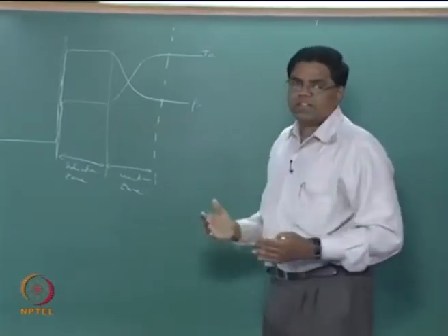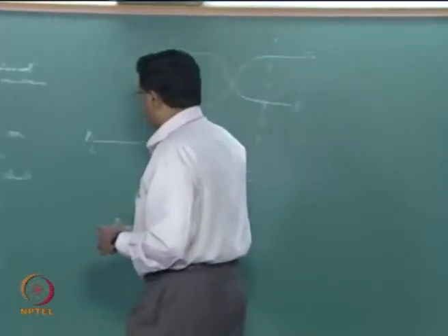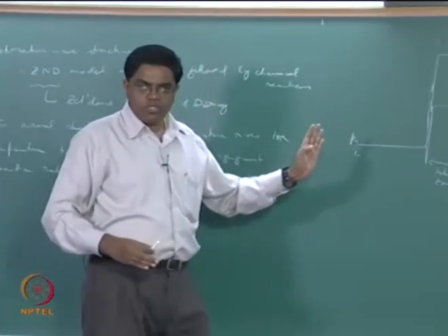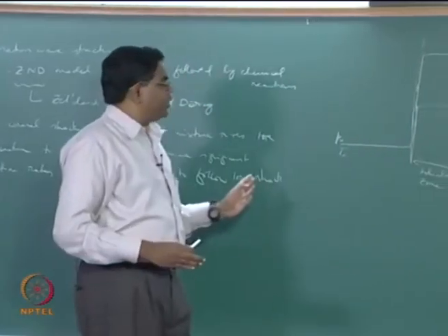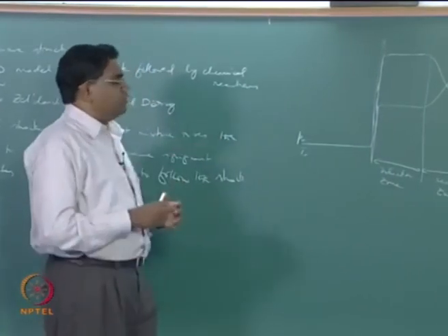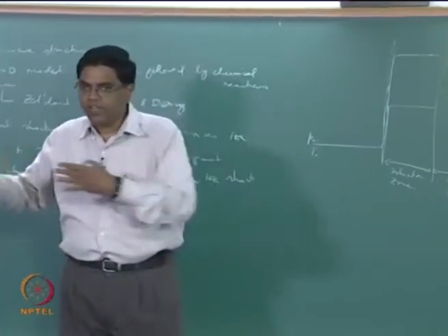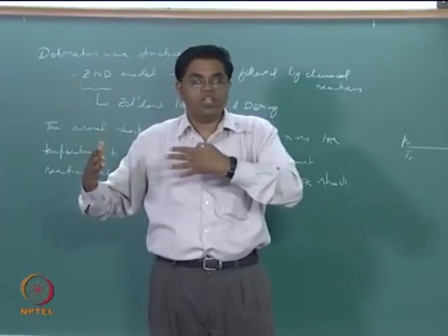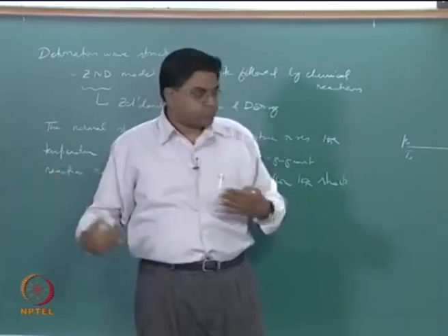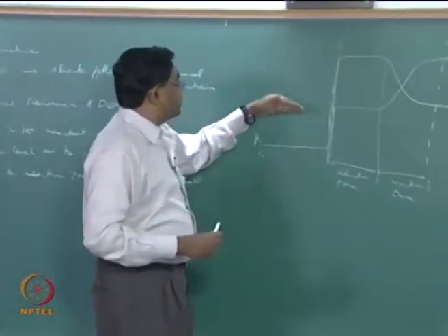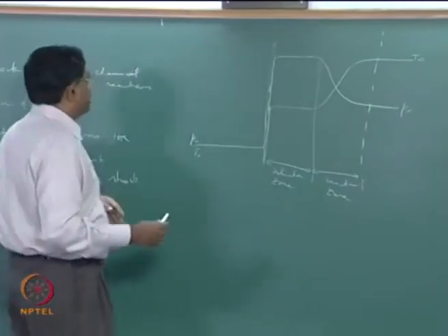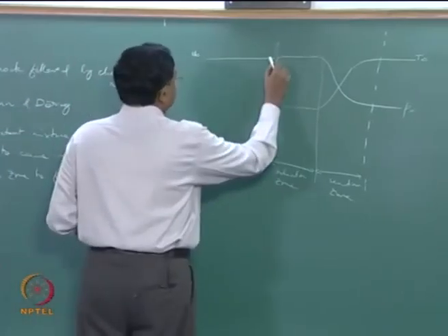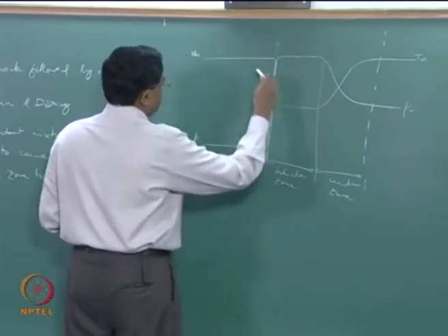Similarly, can we now think about the velocity, right. So across a normal shock the velocity decreases, right, and we are talking about a Chapman-Jouguet detonation wave for most part. In all these detonations we found that the products follow the wave at a velocity, or at a Mach number, that is lower than the incoming Mach number, right. So you have to end up with a lower velocity than you start out with. That means you start with a high velocity, that's your U naught, and then this decreases significantly across the shock.